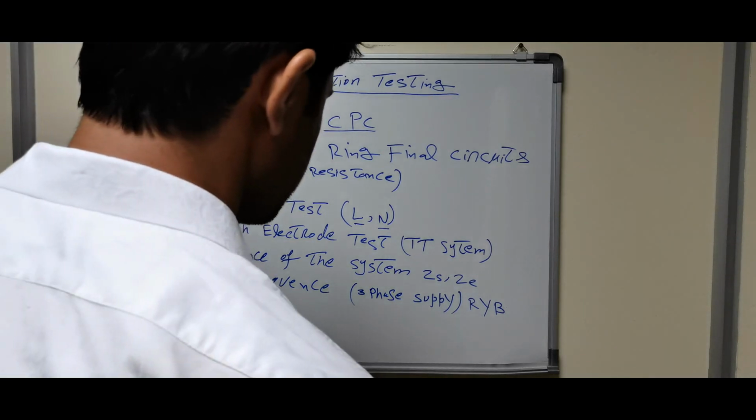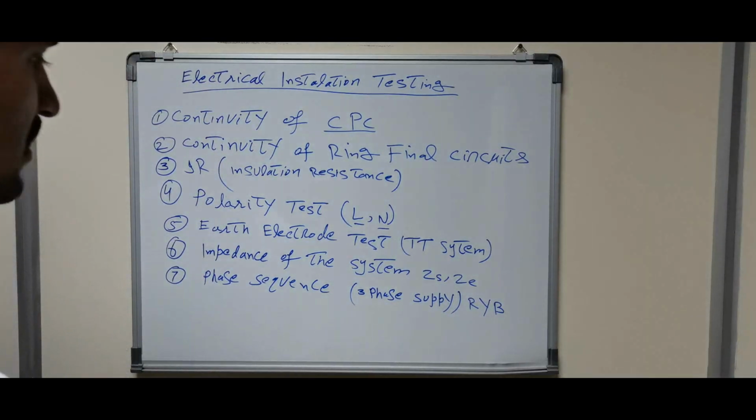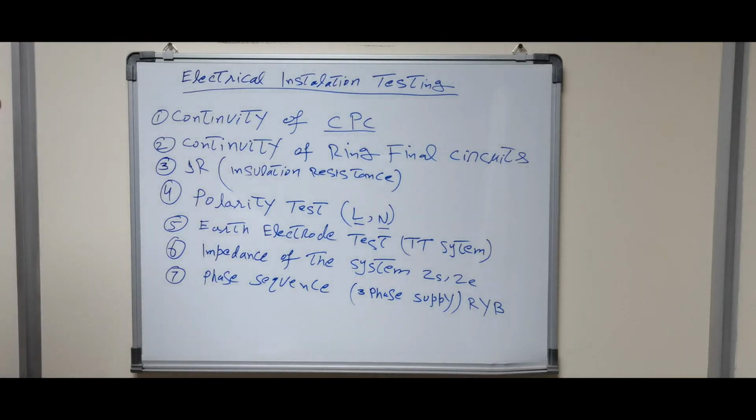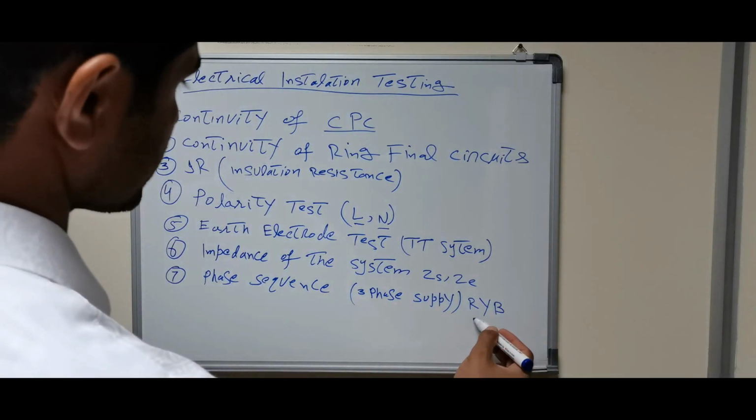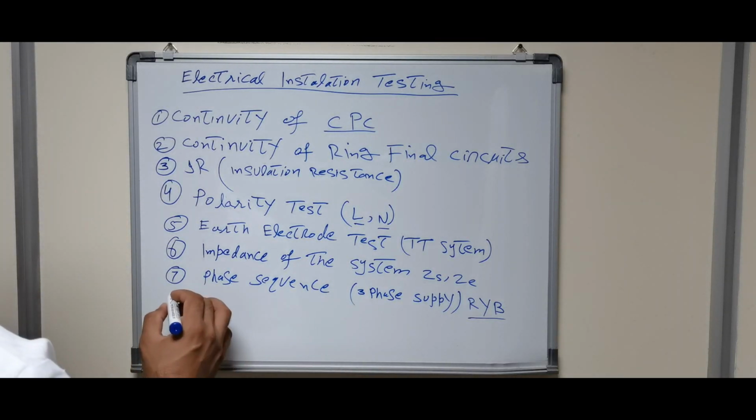Because our three-phase equipment operation is dependent on the phase sequence. For that, we need to ensure the phase sequence of our supply before starting the equipments.